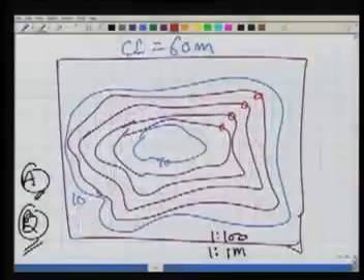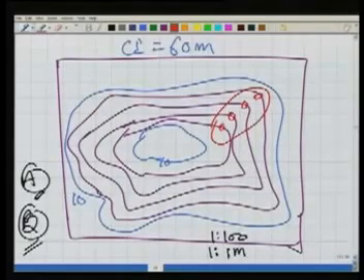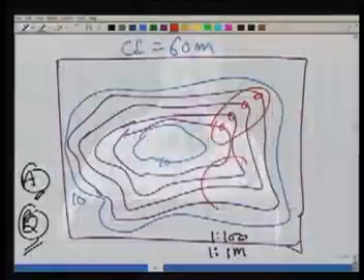However, if my map is very small scale, we are fitting too much information, a large area, in one small sheet. Then in that case, all these will club together. If we are taking a very small contour interval, all these contours will club together. They will just become very confusing, all these lines on top of each other. So we cannot make out the structure of the terrain. So there is no use of going for a very small contour interval for a very small scale map.